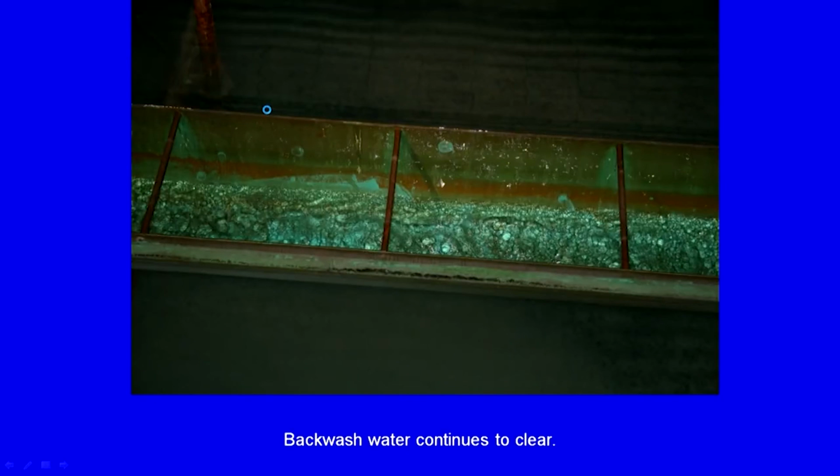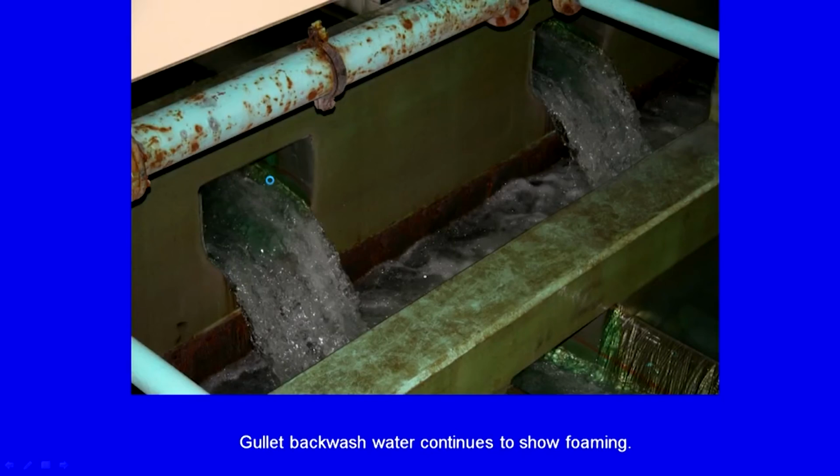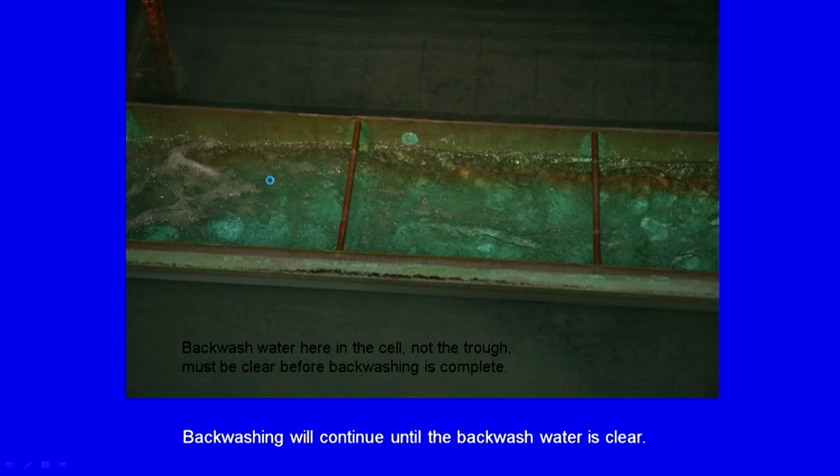Backwash now continues to be clear, and it looks like in this case the backwashing rate was too high, and that is why it is leading to a backup in the backwash trough. You can compare that with the figure here and this backup. This is something you obviously want to avoid. So, backwashing will continue until the backwash water is clear. You can have automated systems, but as you can see, even manual backwashing with manual judgment is relatively decent.